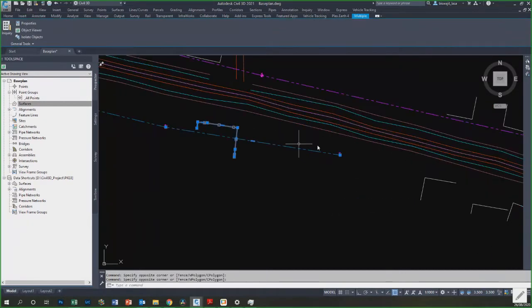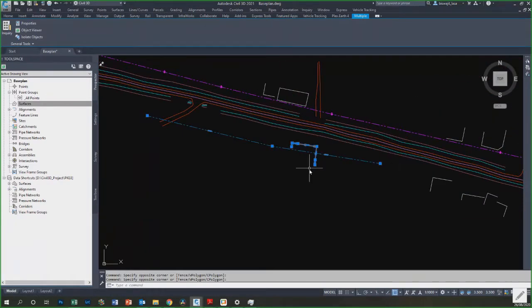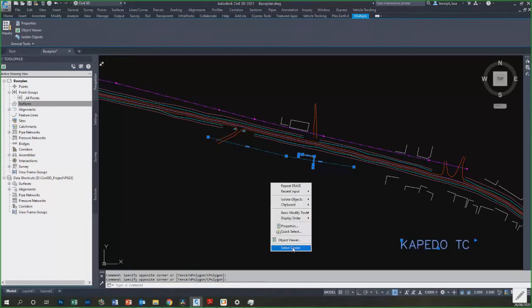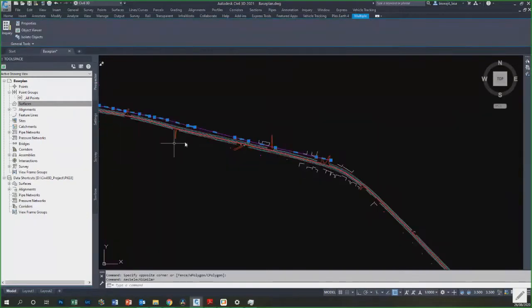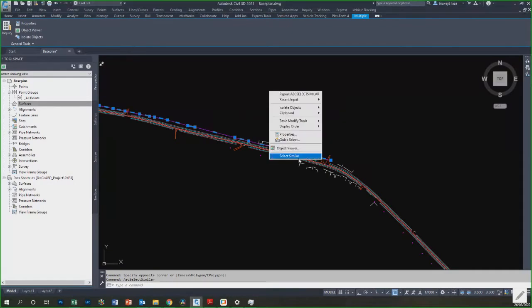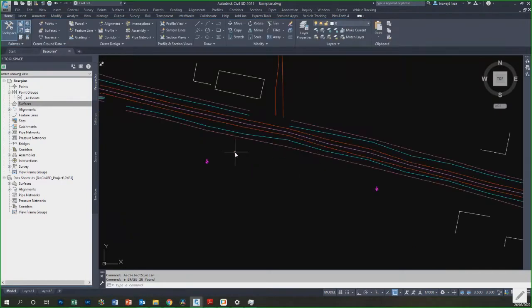These are lines of electric poles, and this will not affect your DTM. So you need to delete all these lines. Remember, whatever points do not have a Z value, or the Z values are not those of natural ground, for example the electric lines, poles, fences, you need to remove from your drawing the ones which you need to create for a DTM.